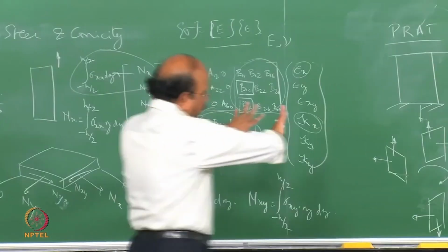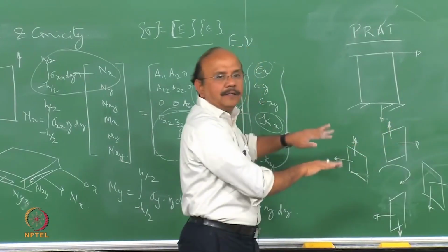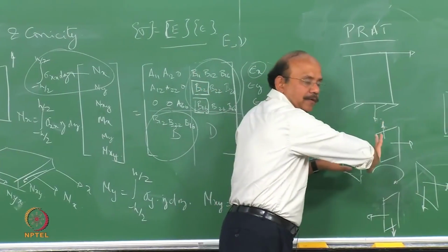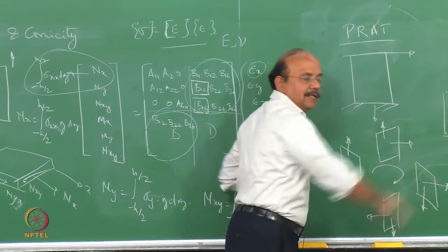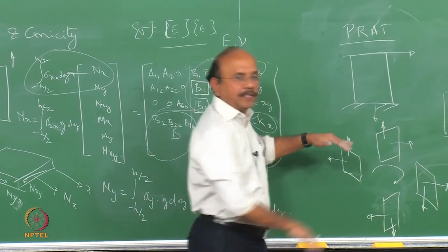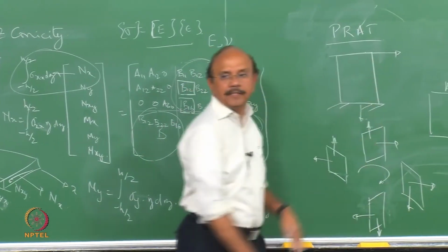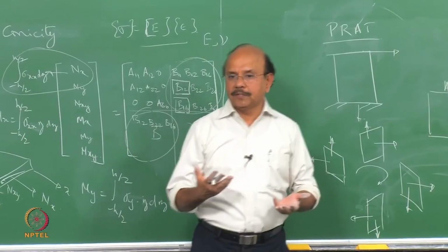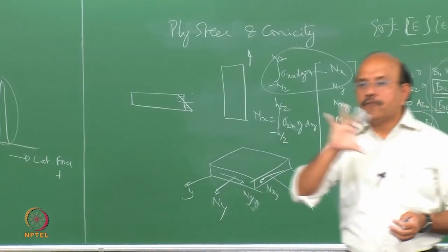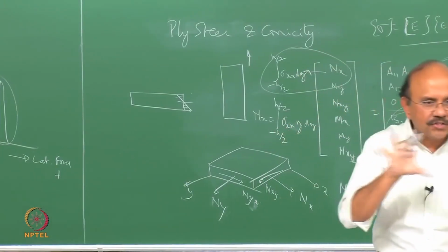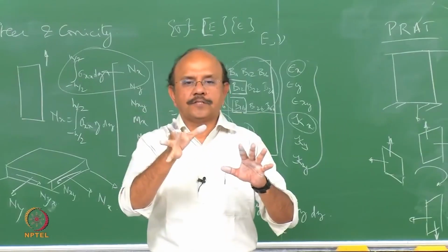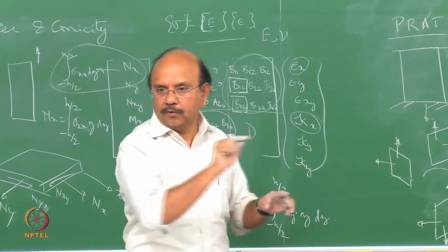At the ends there are shear forces like that, and this is the shoulder region where there are shear forces happening like this, and at the end of the contact patch you have shear forces happening like that, because of which you have coupled forces which come along with these shear forces, and the coupled forces act perpendicular to these shear forces.